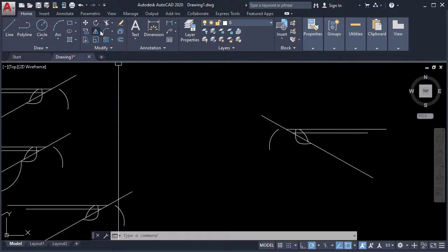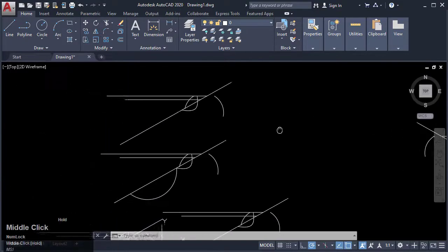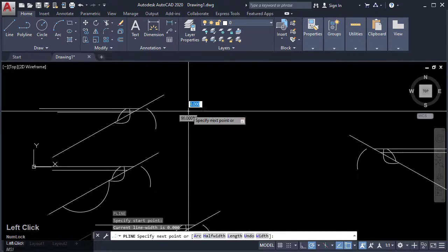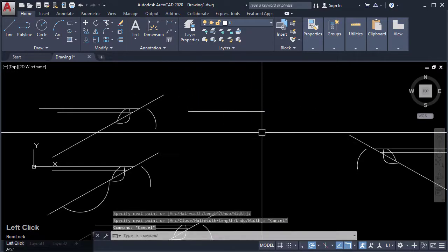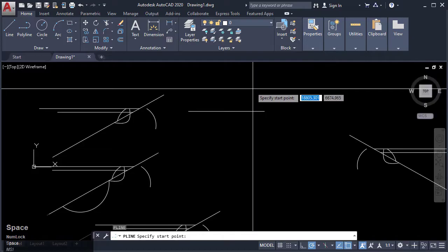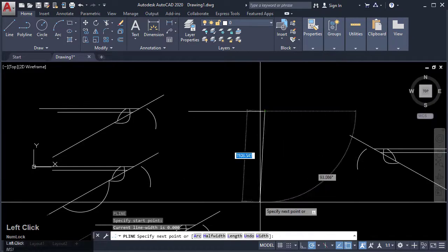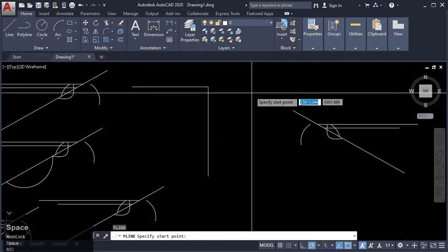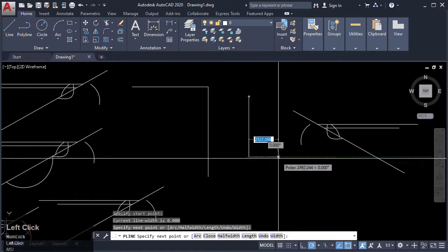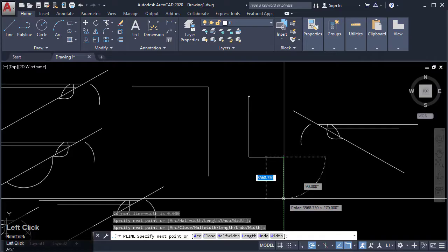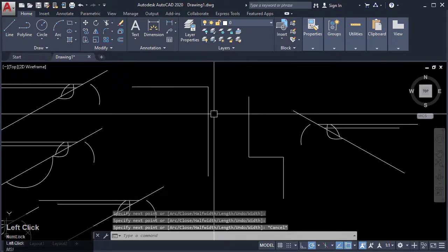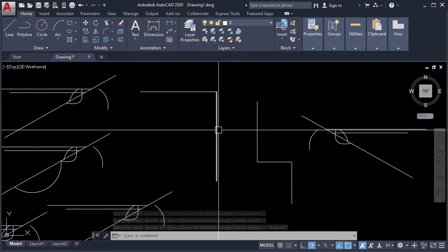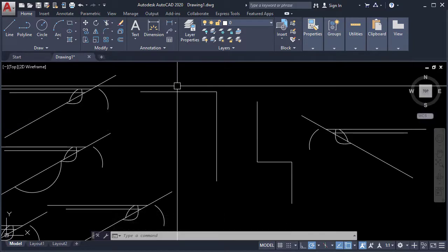Another item is fillet. Now let's say we have a sharp corner. I create two lines, PL, and another line. Or let's say there's a sharp corner again. Create another one. Escape. Fillet allows you to smoothen out the sharp corners of lines and polylines.